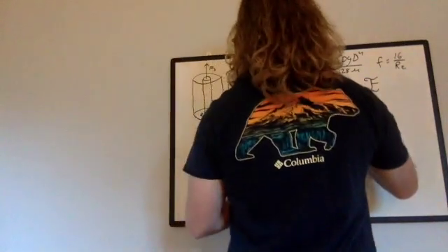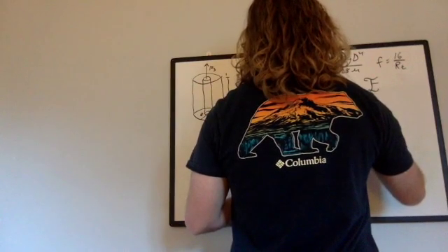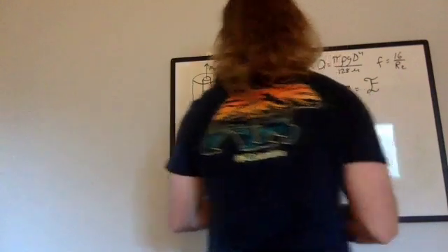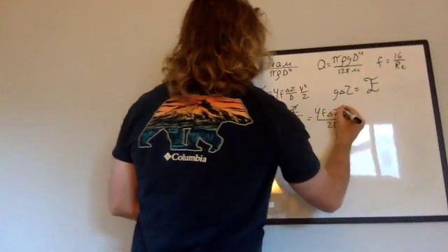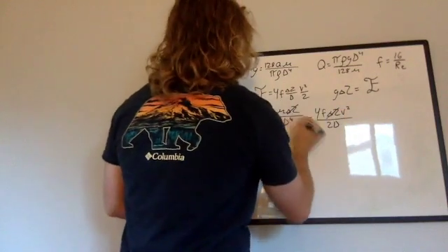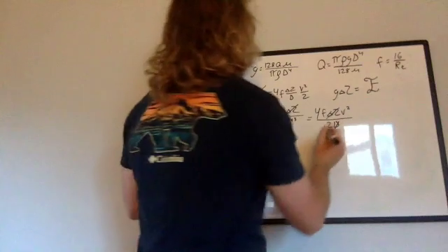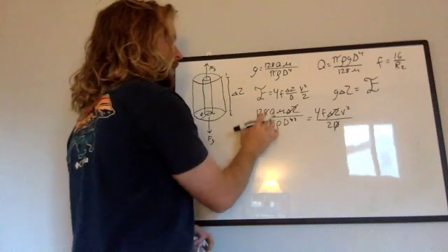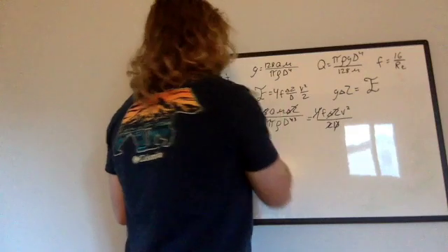So we'll go ahead and write out our right side over here, 4F delta Z V squared all over 2D. And now we're going to go ahead and cancel some things. Our delta Z's are going to cancel over here. This D to the fourth would become D to the third and cancel out with this D right here. And then this 4 over 2 would simply become 2, which we would divide over to the other side and get 64 on this other side. So this 128 would become 64.